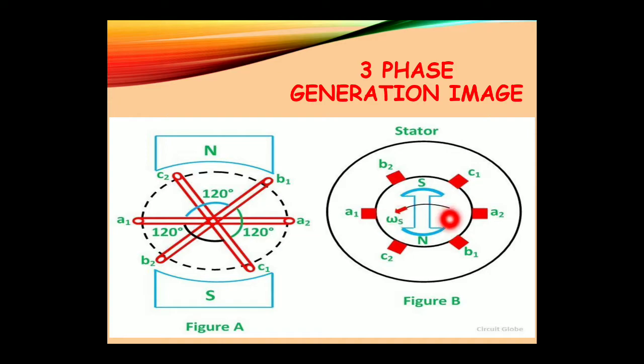And now you can see here, if the magnetic flux is rotating in nature, that is the rotor of an alternator, it is a projecting pole type or salient pole type rotor of an alternator, and the rotor is the field of the alternator, and when it is in rotating mode, the static conductors cut the flux.